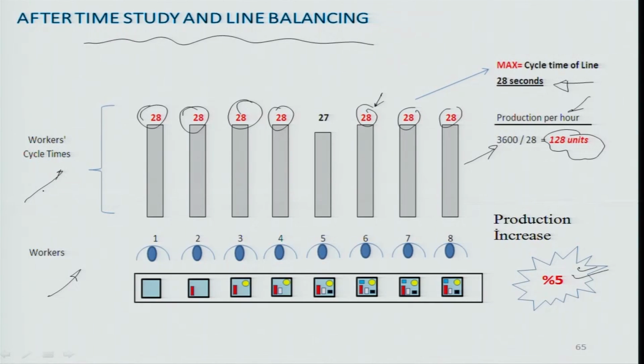So, that is the basic concept of line balancing. You adjust your tasks in a manner so that overall the slowest step of the assembly line, or let us say the highest cycle time step, is shortened, and there is almost a leveling of all the workstations in terms of time scales, so that you can now predict the maximum production rate. This way the production rate can increase by cutting down all the slack.